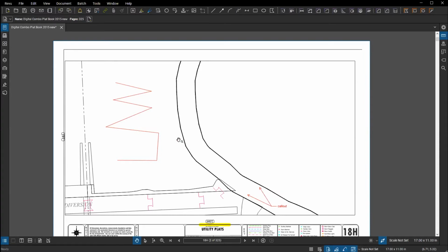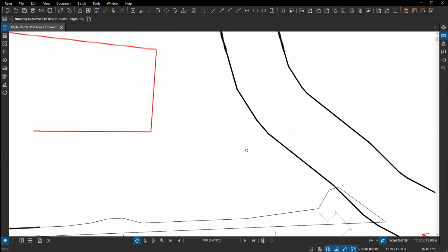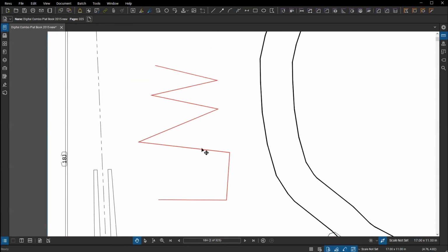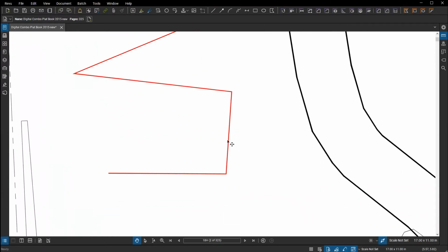Now, a similar approach to what I just did with adding leaders into the callout. You may have missed some points as you're defining the path. This was supposed to come in, then out this way versus straight up. So along this edge here, I want to introduce another control point so I can then manipulate the path being used for that profile being drawn in here.